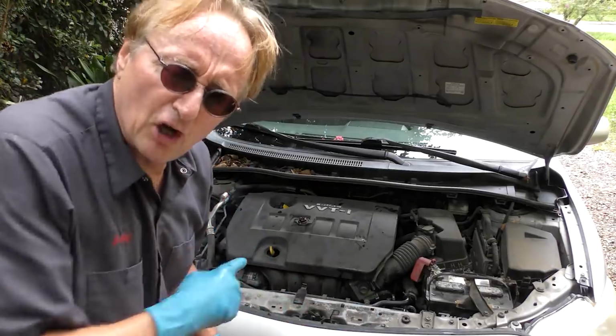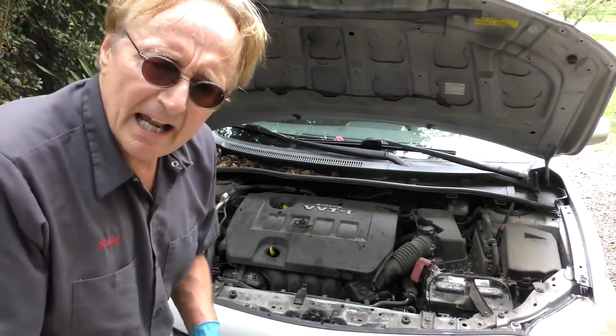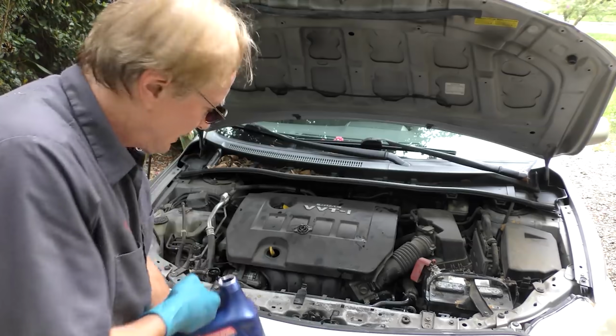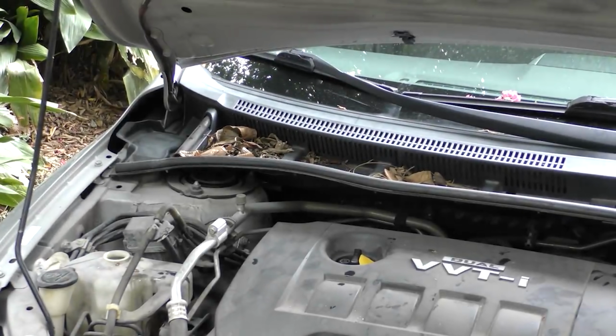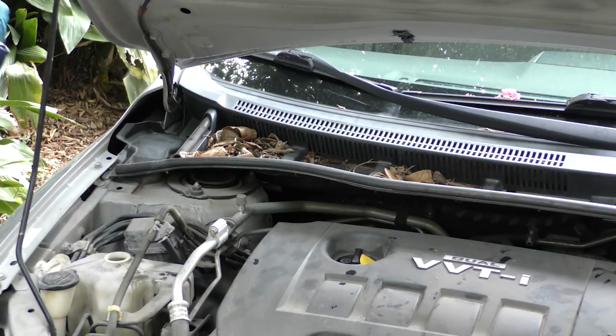Turn the AC on full blast so the fan's blowing, and then pour it as the air bubbles come up. It might take a few minutes. And don't forget to fill the reservoir too halfway, right in here. And put the top back on. Now we're on to part two.